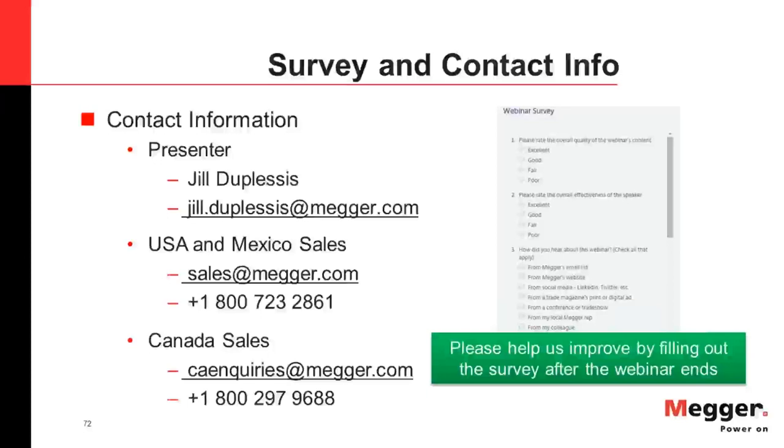Well, during the presentation, Jill mentioned a couple of things related to negative power factor results. That is a common thing to get. It's an unrealistic result and could be caused by three major things. One is design, specifically in circuit breakers with SF6 insulation.